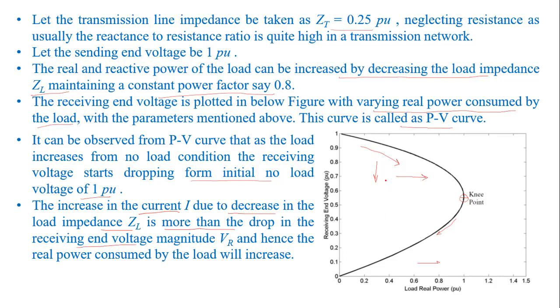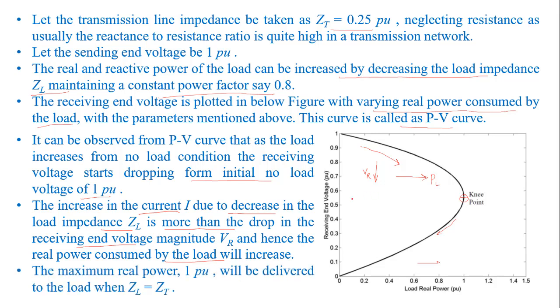Therefore, your PL is increasing whereas VR is decreasing. Hence, the real power consumed by the load will increase. So, in this particular region, your PL will increase and VR will decrease because the increase in current is more as compared to the decrease in the receiving end voltage. Okay, so therefore the PL is increasing and VR is decreasing.